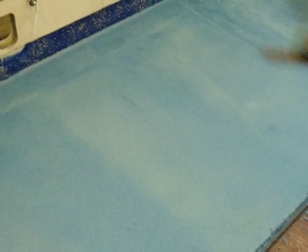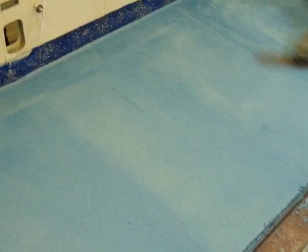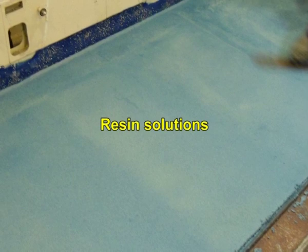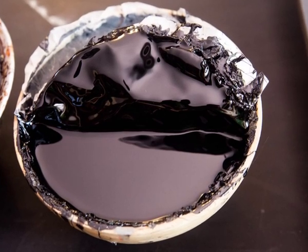If the product is not compatible with bare metal, the interior can be flushed with waxy type formulations or with resin solutions. Although the resins or lacquers are usually sprayed on, a tube with an epoxy lining costs about 25% more than the same tube uncoated.